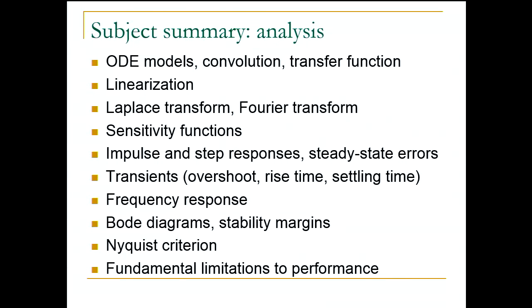In time domain, we talked about how an unstable zero would always introduce an undershoot, right? And in frequency domain, we talked about how Bode integrals limit what's achievable in terms of shaping the sensitivity function. So we saw that if we reduce the gain of the sensitivity at low frequencies, then that will increase the gain of sensitivity at some other frequencies, right? That's a fundamental limit which you can't overcome with any linear controller. So this was all part of analysis, right?